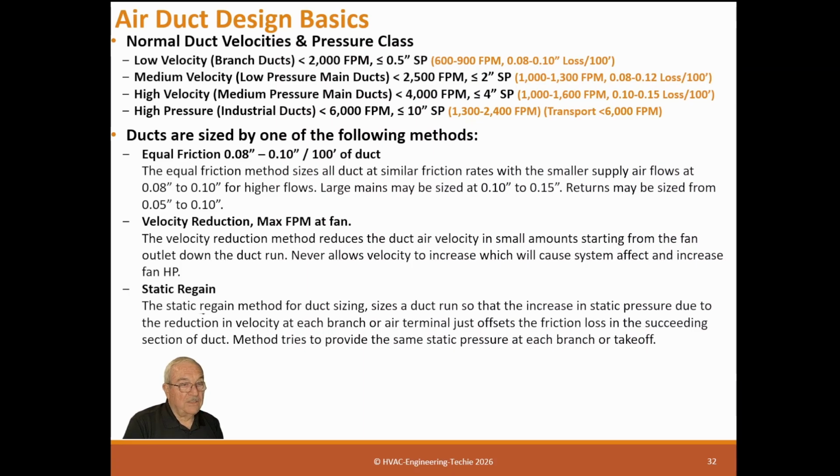I have had a job or two early on in my career that had to have equal pressure. It was an industrial job, and it was very critical. So I did it by hand. It was a large duct system, and we actually put in orifice plates where we knew we were going to have to eat pressure up for something, and when you turned it on, it was already balanced. It was self-balancing. But boy, did it take a lot of work.